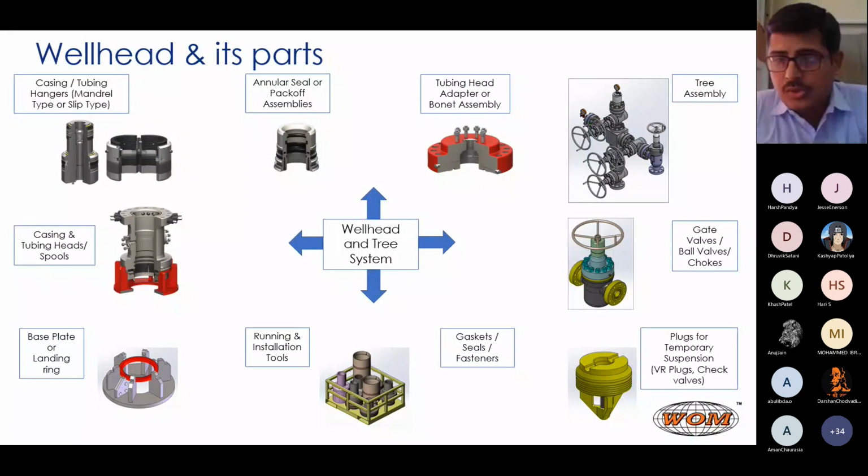Then you have the wash tools. When you are drilling, you will be using a lot of muds. There will be a lot of debris and everything which will contaminate the wellhead internals. So it needs to be washed from the surface. So we have the wash tools. Once you rig up the BOPs above the wellhead, it needs to be tested to check the integrity, that everything is perfect. You have the BOP test plugs to run it. So there are a couple of running tools we supply along with the wellhead for the successful installation in the field.